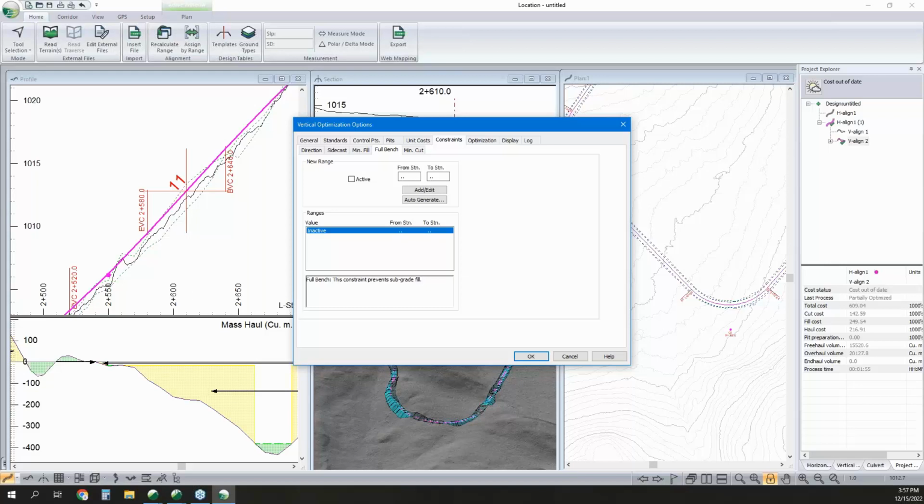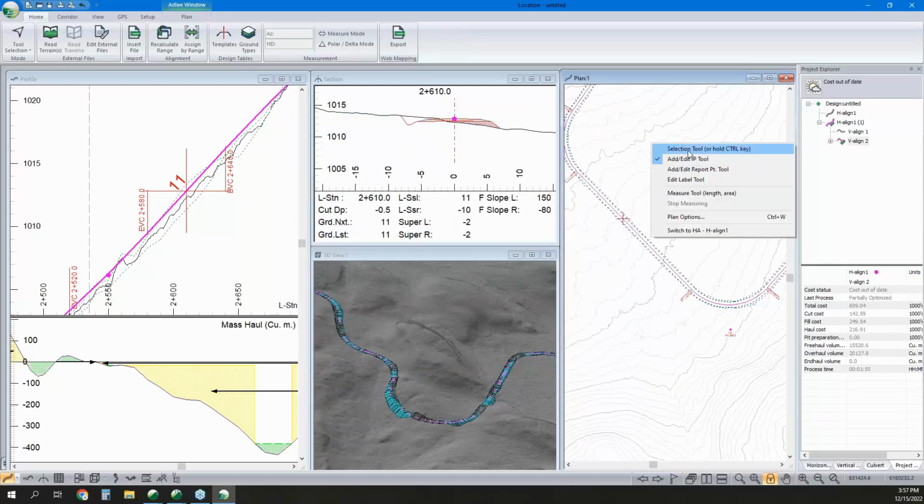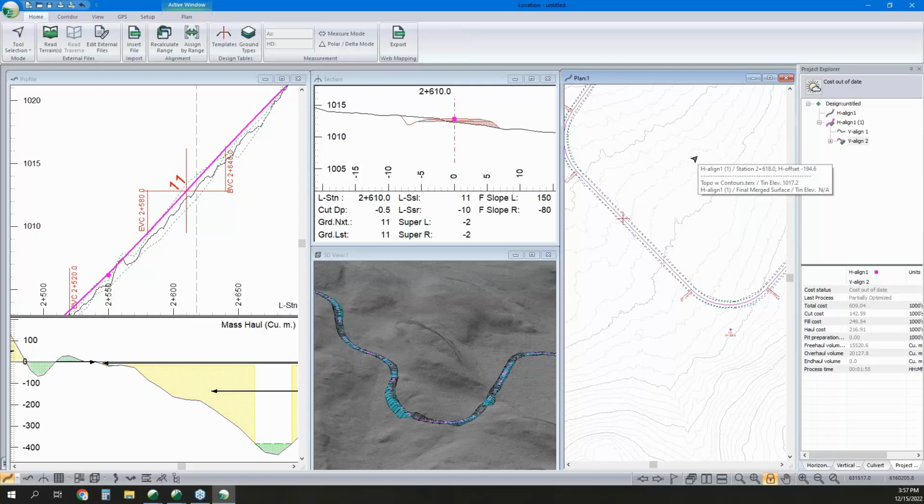Sorry, just one last thing for that, Matt. If your geotech recommendations have a spatial component to them, you can bring in a KMZ, shapefile or what have you, and actually see that in the background for where those different prescriptions are assigned, and you can make your changes without just guessing what they mean, or using some station location that may be out of date, so you can have the georeferenced information in there while you make the changes.